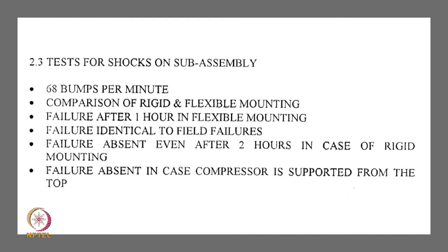Failure after 1 hour in flexible mounting, and failure identical to field failures, was the part that led us to confidence that flexible mounting was indeed the cause. We had railways come and witness this test, so we could have their confidence that our analytical approach was leading to something which would have an impact on the field.